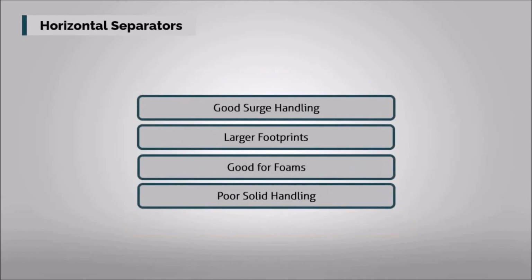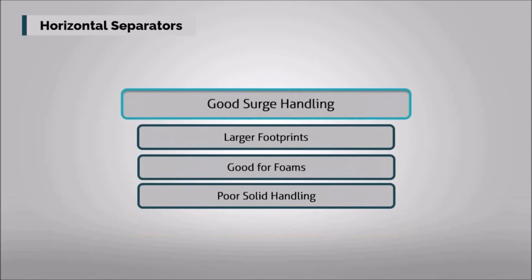Turning to the horizontal vessels, they are more economical for normal gas to oil duties, and especially when there is a tendency for the oil to foam. The necessary aspects relating to horizontal separators are as follows. Large horizontal separators provide better surge handling and slugging abilities than small horizontal vessels and, of course, vertical vessels. Then, although horizontal vessels require more floor area, they are easier to mount in a modular format. For certain applications, processing modules are receiving renewed interest, particularly when anticipated production lifespans are small.